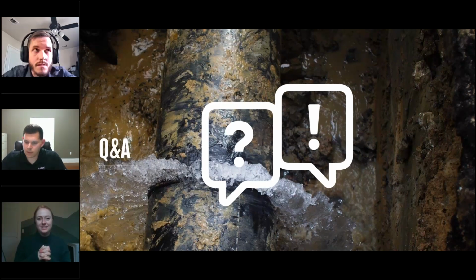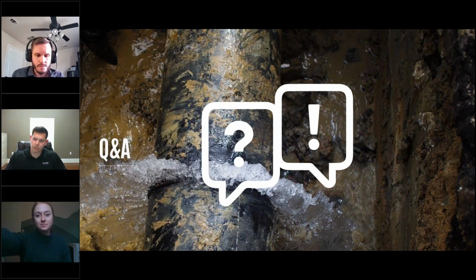I guess we'll stop in the middle there. So the first part was, is it always recommended to place them between your components? Not necessarily. It's not a permanent installation, I would say. First off, these sensors can be moved around. So if it's more helpful to have data at each location, we do recommend that sometimes. But between your components is usually where you have an open tap or something that's easy to connect to. So that's generally why you see your sensors and transmitters installed in between your stuff like that.